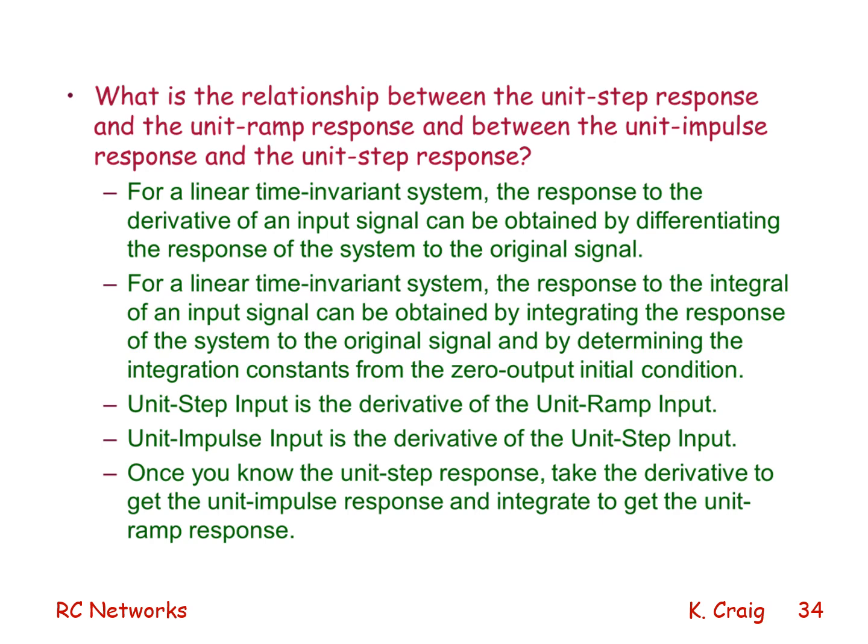For a linear time invariant system, the response to the integral of an input signal can be obtained by integrating the response of the system to the original signal, and by determining the integration constants from the zero output initial condition. The unit step input is the derivative of the unit ramp input. The unit impulse input is the derivative of the unit step input. Once you know the unit step response, take the derivative to get the unit impulse response, and integrate to get the unit ramp response.